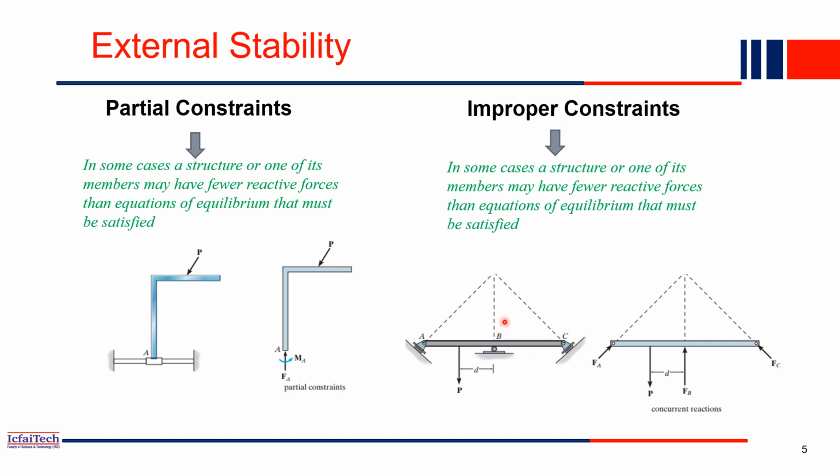If you apply a small external side force, maybe an inclined force, this member will rotate, although it will satisfy the three equations. So how many unknowns are here? Here you have three unknowns, 1, 2, and 3, because all are roller supports. So basically it is still a determinate structure, but it is not stable.